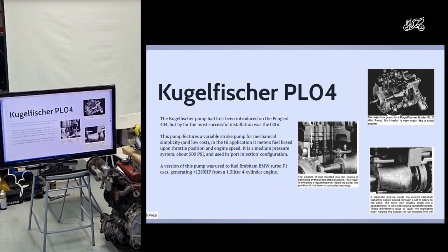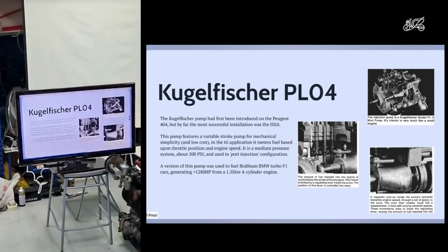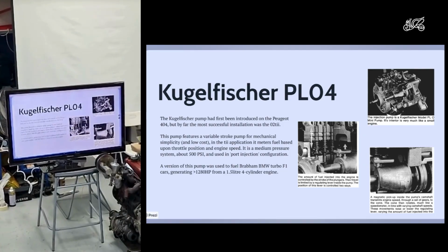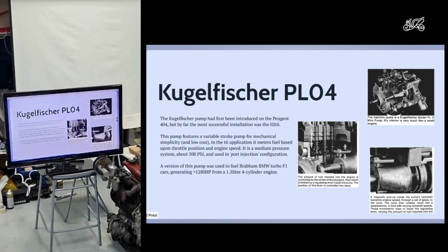by adjusting the stroke. So in an engine, the stroke is normally fixed, right? So as the piston comes down, the amount of air we suck in an engine is the same every time, right? So what they did in this case is they have a little piston for the injection, which is going up and down, and they're adjusting the stroke. So at low speeds, the stroke is small, just pumps in a little bit, and at high speed, the stroke is big and it pumps in a lot. And they found a way to do that, which was relatively cheap to manufacture, much less precise moving parts, and therefore more suited to mass market.